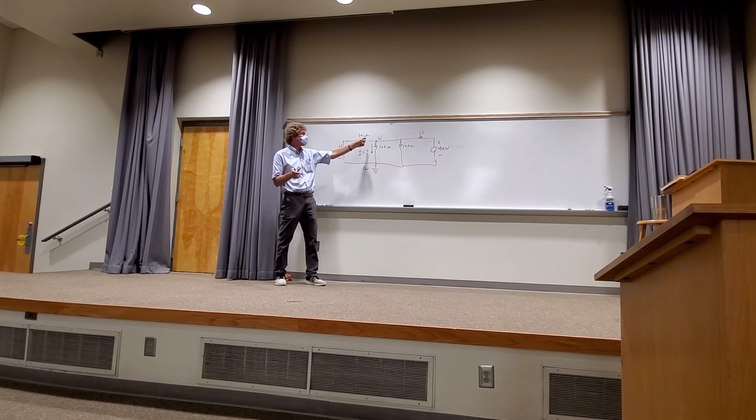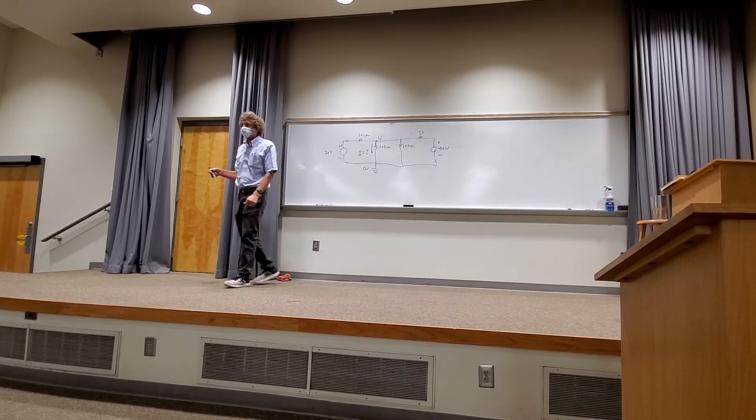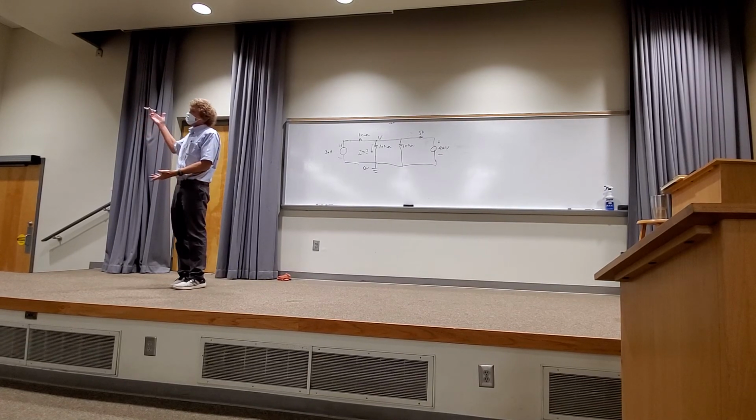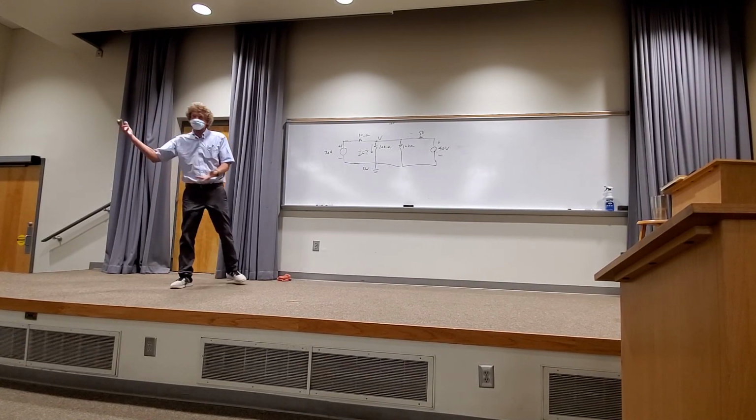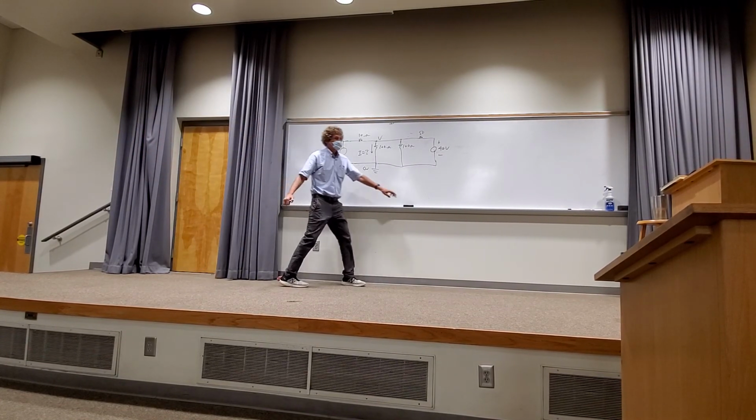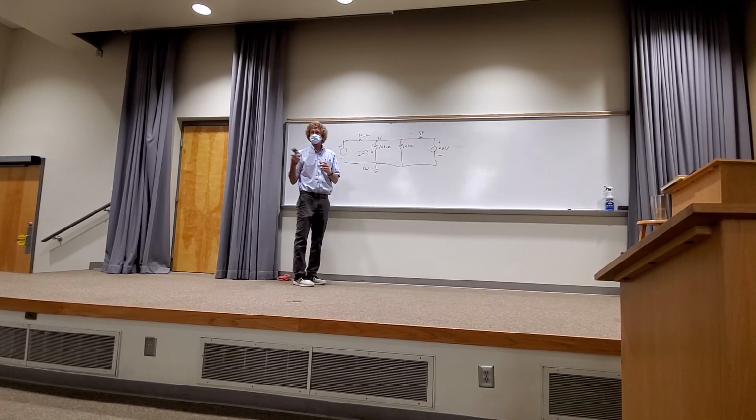I know if I have that voltage, can I get this current? What would it be? Say that again? V equals IR. Well, that current would be V over 100, right? If I knew the V, I got the current. Y'all agree with me? So let's go get the V. How would I get it? There's one thing I would do to this circuit.